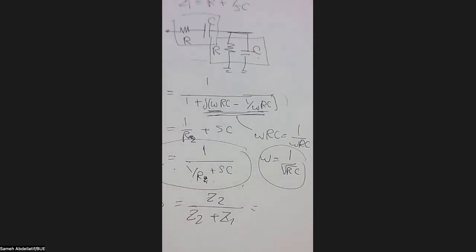Of course, we don't have inductors here, so it appears whenever you have a capacitive part. So by having the same beta network, you can have the same oscillating frequency, but take care, this is considering that your amplification network is frequency independent, as in this case. So this is typically what we have in the beta network.